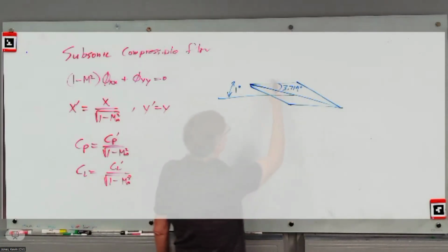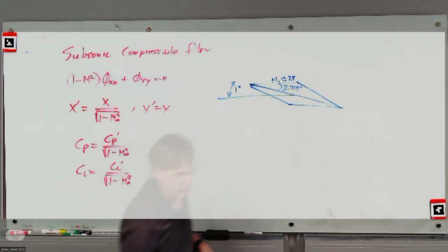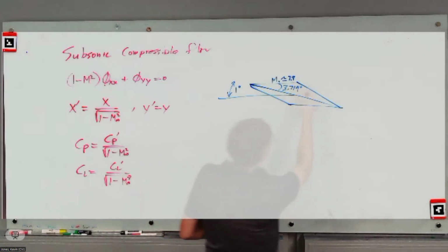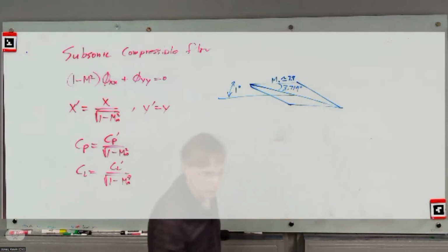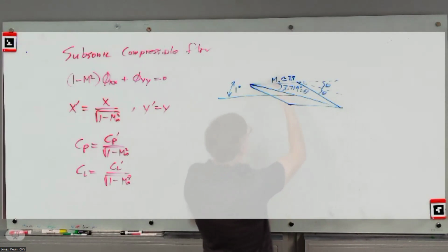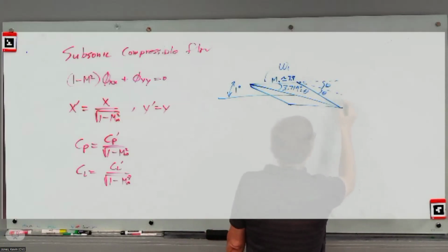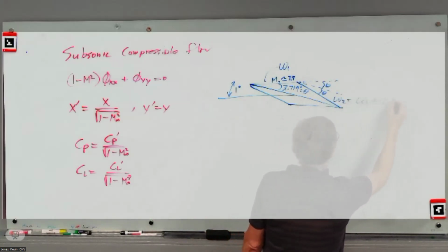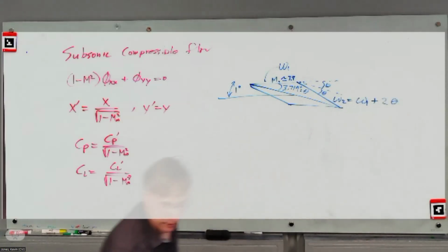We had a Mach number here. We solved something like 3.8, I think. To get from here to here, does everyone understand where that came from? Figure this out. They're both the same as this. So whatever our Prandtl-Meyer function is here, this one, omega 2, is omega 1 plus 2 times theta. Does that make sense? Everyone got that?